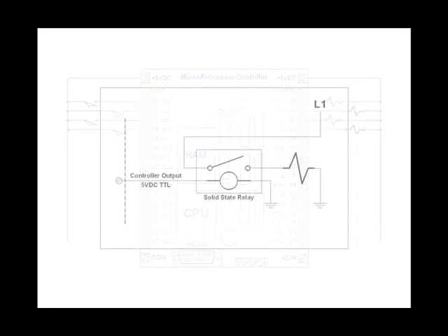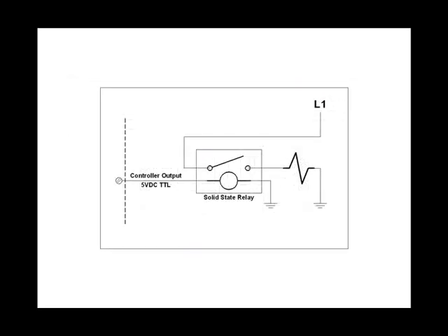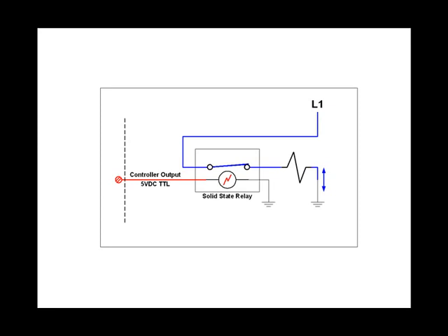These solid state relays with isolation are connected between each output device and the 5 volt output signal environment controlled by the program in the controller, which is stored in the RAM. When it goes high, the solid state relay switches the field voltage L1 across the load, in this case 115 volts AC. These devices have absolutely no intelligence, artificial or otherwise. They simply interface 2 different voltage environments. In this case, controller output 5 volt DC TTL level to 115 volts AC line.